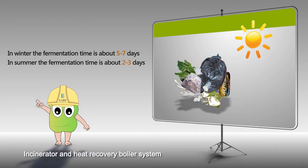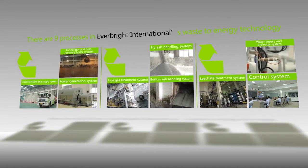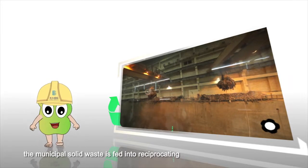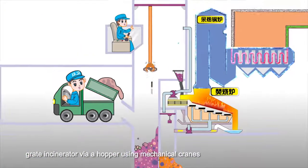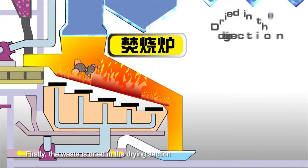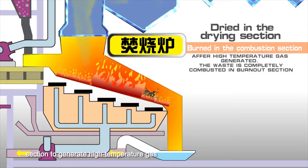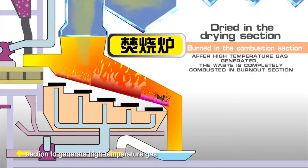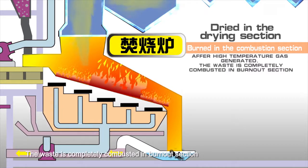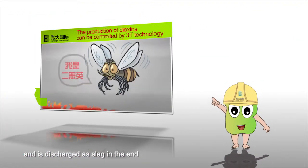2. Incinerator and heat recovery boiler system. After the fermentation, the municipal solid waste is fed into the reciprocating grate incinerator via a hopper using mechanical cranes. Firstly, the waste is dried in the drying section. Then the waste is burned in the combustion section to generate high-temperature gas. The waste is completely combusted in the burnout section and is discharged as slag in the end.